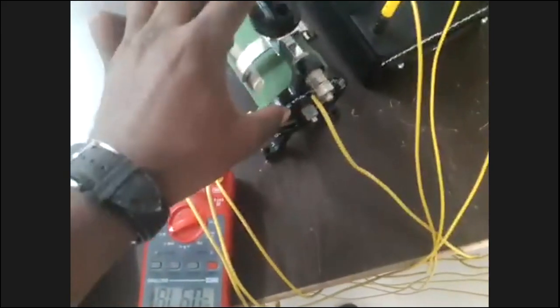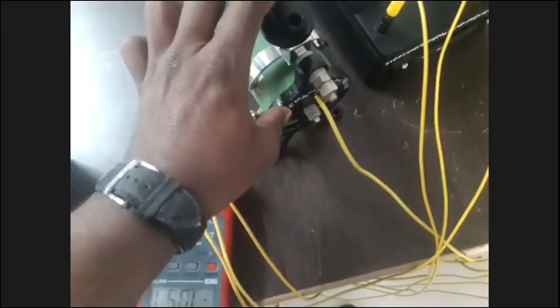Okay, we will switch off the MCB. We will do the reverse procedure, vary this rheostat to initial position. After that, okay, see, we have performed the running test. Now while doing the calculation we require the armature resistance. आपल्याला armature resistance लागतोय. So we will calculate the armature resistance after conducting the test.